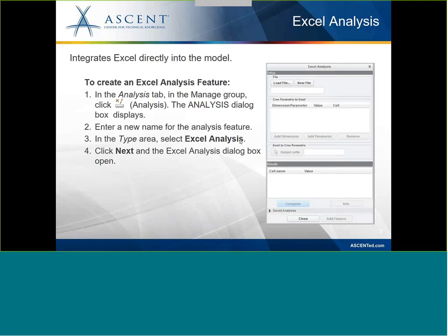There are actually two ways that you can create an Excel analysis. You can just flat out create an Excel analysis, but when you do that, it doesn't create any parameters. If you create an analysis feature and select Excel analysis as your type, that provides you the ability to create those parameters that you want to use.